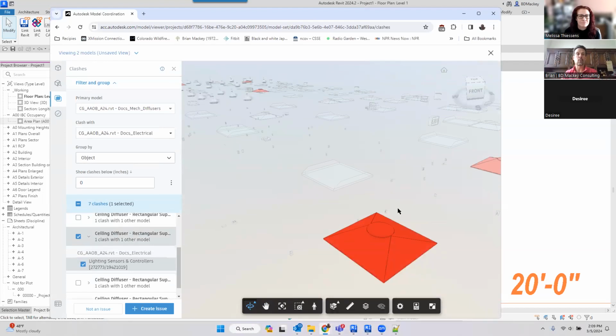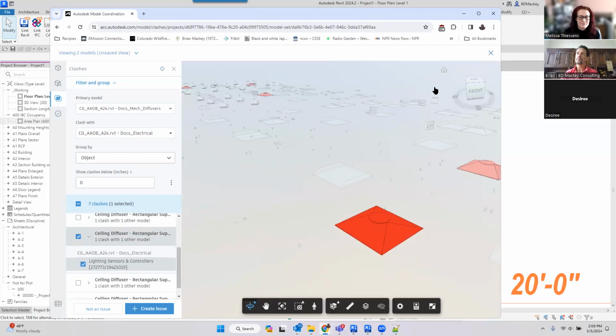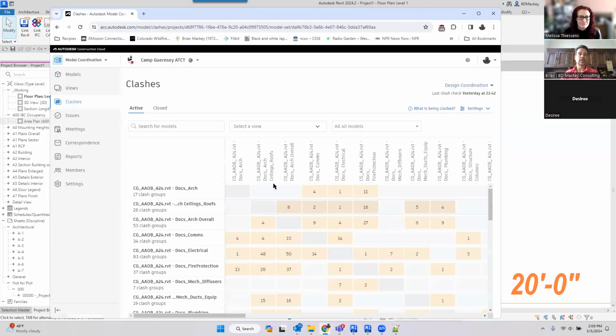So part of the BIM coordination meeting is they call them out saying, hey, look, electrical guys, you haven't really coordinated. Let's go through and get that up. Right. And it's really cool. And you look on here, you've got this nice little tree form. Again, it's however you set the views up in your model. It does clash view to view. So if you don't set up views, it's going to clash your entire model.